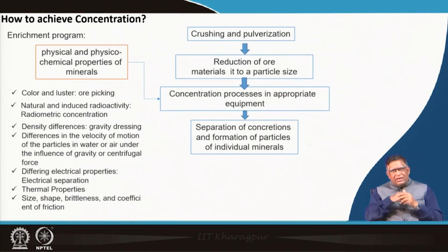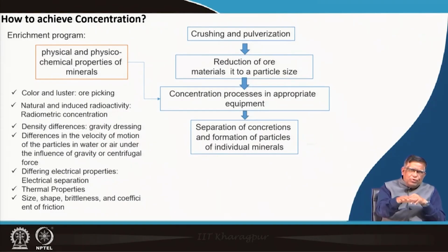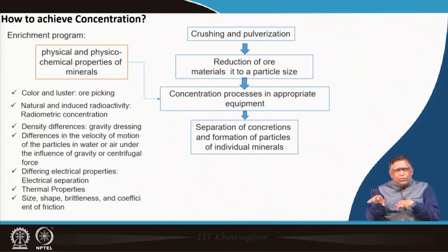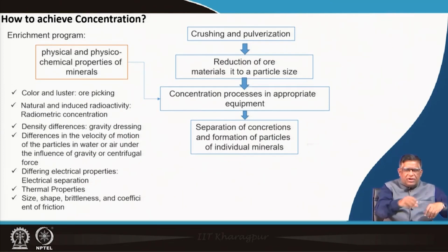Today, that thing has been done with the advancement of imaging techniques, online weighing techniques, and X-ray and XRF, which can be done while the material is slowly moving on the conveyor belt. They can be scanned, you can make them in a monolayer to go, and in between you can have an arm to push them, so that only the valuable minerals will go.